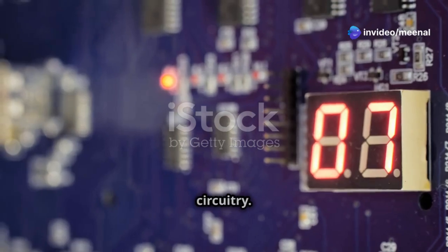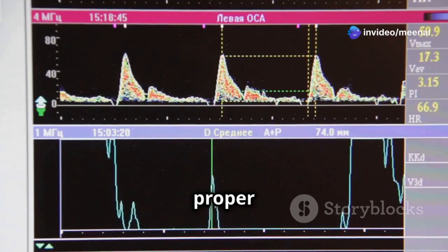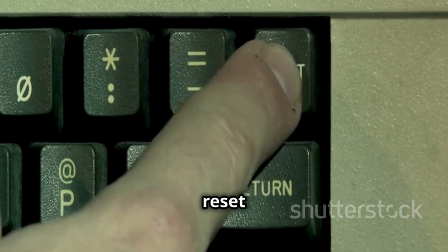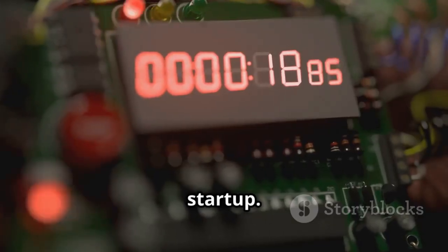Timing is crucial in reset circuitry. The reset pulse width ensures proper system initialization. If the reset signal is too short, the system may not reset fully. If it's too long, it can delay startup.